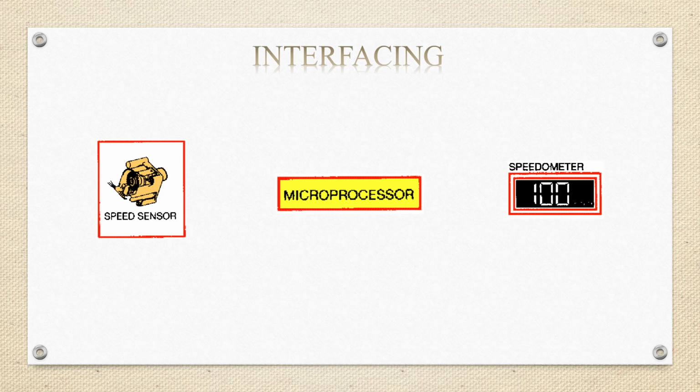And every time a certain number of revolutions or pulses occur there, it translates into miles. And if I'm comparing those revolutions to time, I'm timing them, then I know how many revolutions of my axle I have and how many revolutions happen in 1 mile. I can do all the math with my microprocessor to translate those pulses coming from my speed sensor into miles per hour.